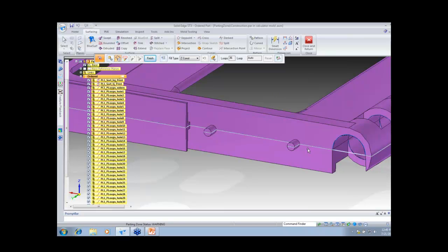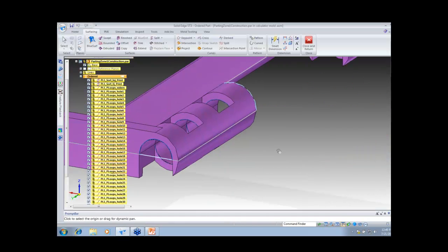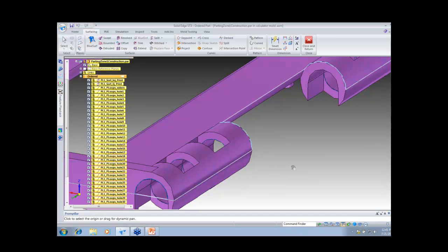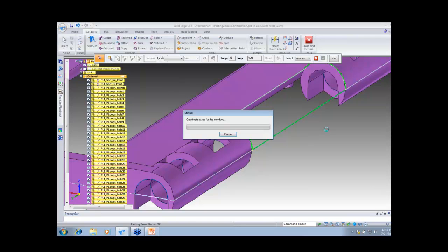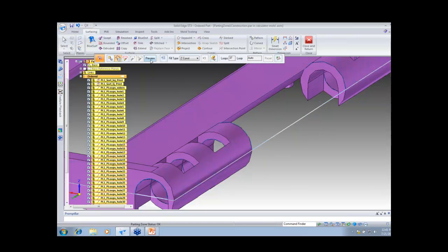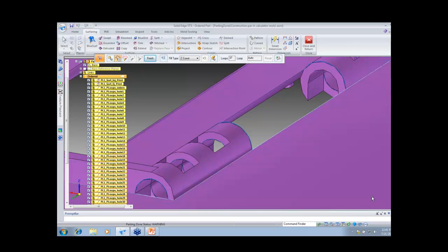So previously our parting line was going from the top, but here you'll notice that it's going straight. Because I added the loop, now I made some changes. I'm going to do this again on the other side. This time I'll add a loop inside this cutout. So I'll just say add loop and select these 2 points and hit accept. And now I can run this iteration again to accommodate all the changes. And by doing that, you'll see it creates the external surface instantly, and everything looks good.